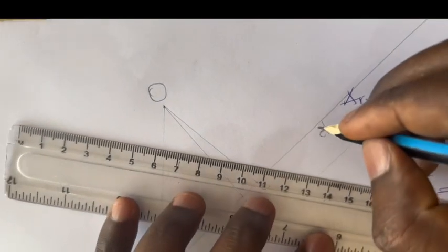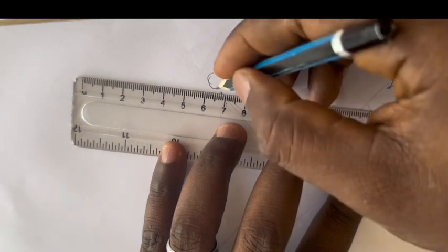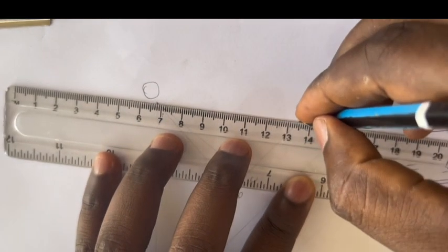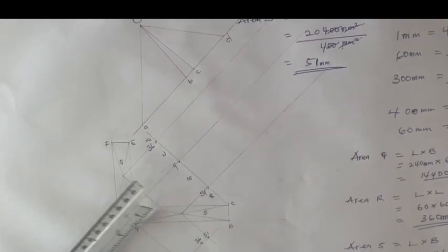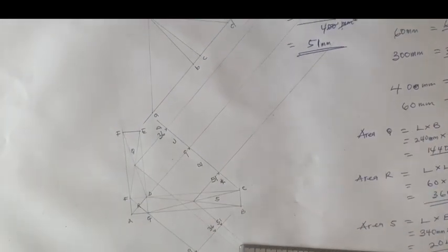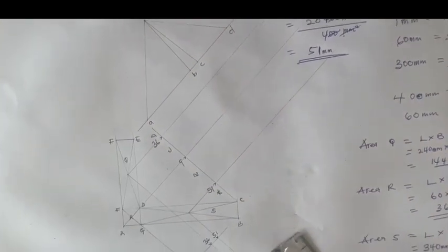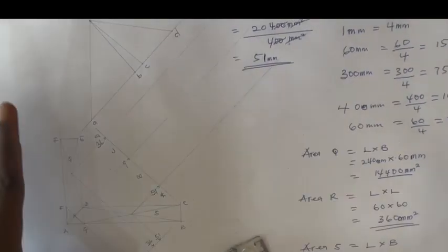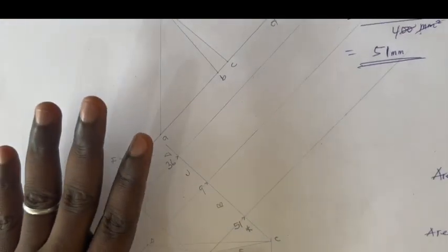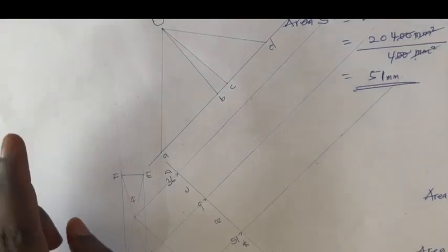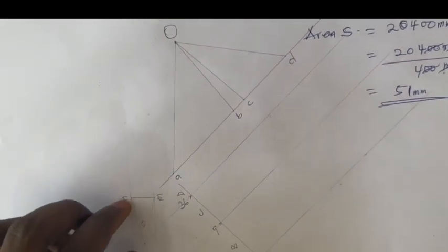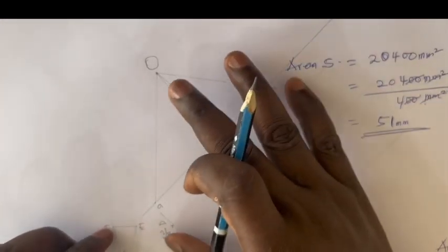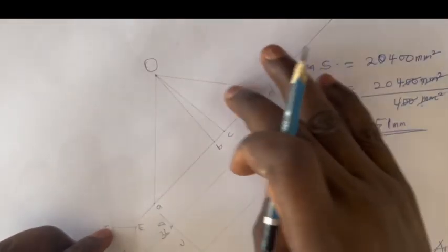And then O to D will give me this. So I have O to D, right? Okay. Now that I have gotten this, there is a need for me to draw what we call the link diagram or link polygon. It is not link mechanism, it is link diagram or link polygon. And this will be drawn using these lines that I have over here, my lines on the polar diagram. This diagram is called the polar diagram, right?